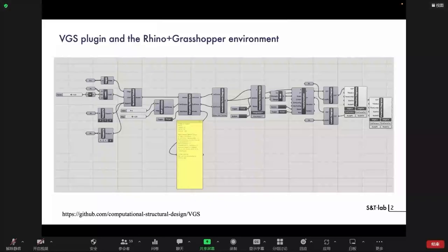And then, as it is not a form-finding tool, you need to feed all that data, and the plugin will evaluate equilibrium if it exists. So if it doesn't exist, you need to parameterize the data differently to achieve the equilibrium.